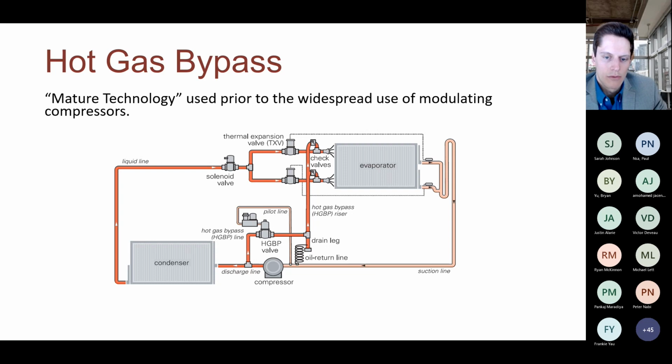So when we have a DX coil, we want to put all of our air through that DX coil, dehumidify to a certain dew point, and then reheat. So it gives you much better control. So don't be confused when you see hot gas reheat, hot gas bypass, DX coil bypass. Those are all very different methods. But really the key one to remember is just hot gas reheat is a good thing. Most manufacturers are doing that. Hot gas bypass and DX coil bypass are far less common.